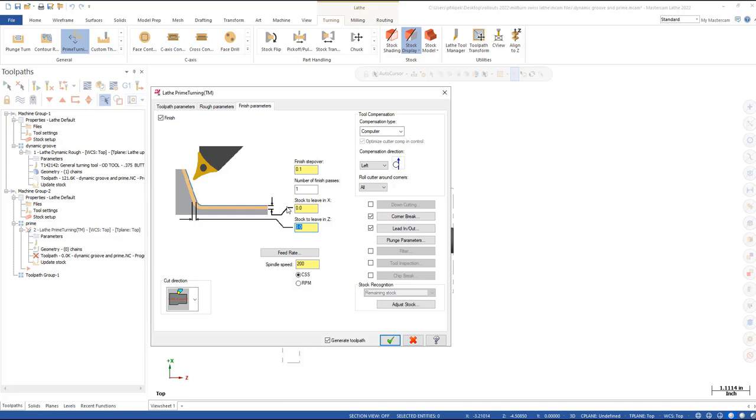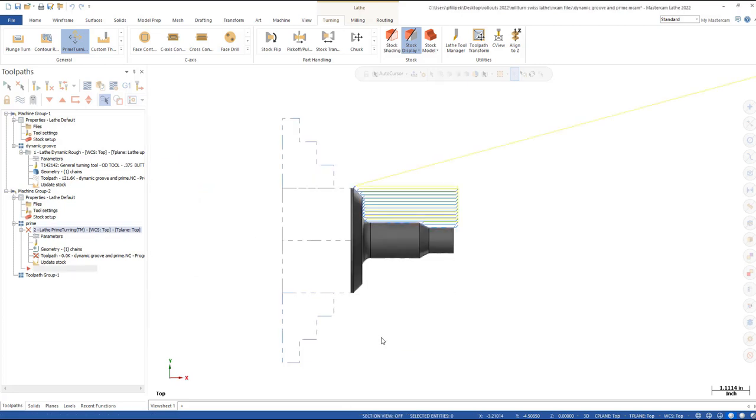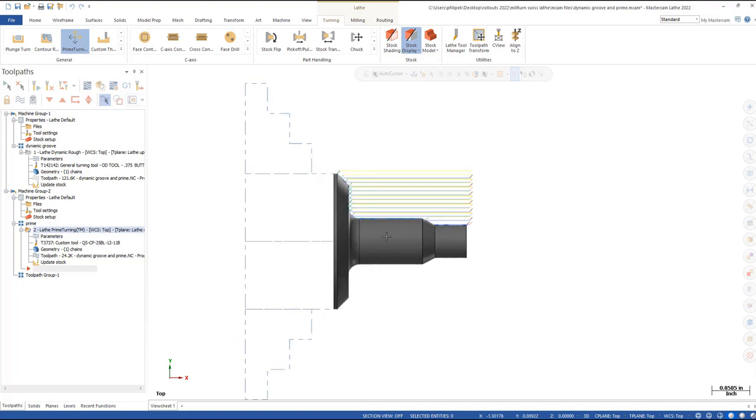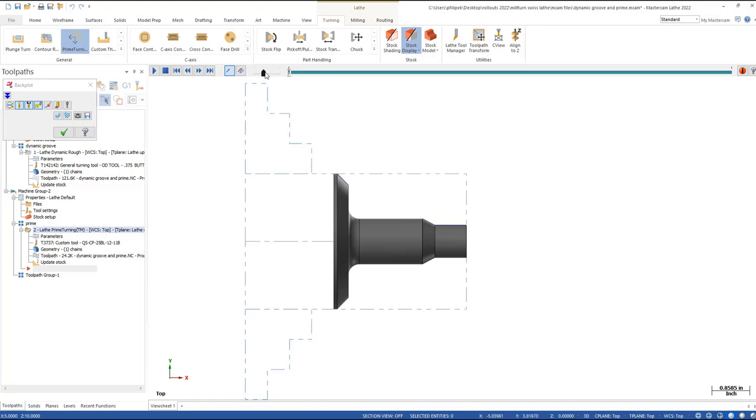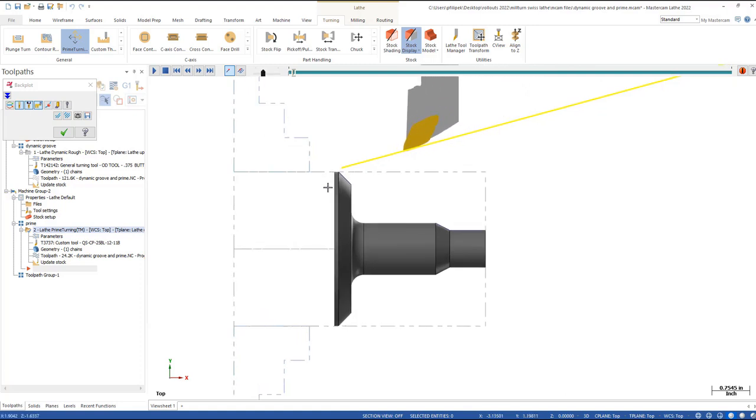Now, if you wanted to work from face into chuck, then you just chain it that way and the toolpath will work accordingly. So if I go ahead and green check out of here, I have this really nice looking toolpath that's going to scoop this out as it goes. And we'll see that toolpath come down. And there is that insert.